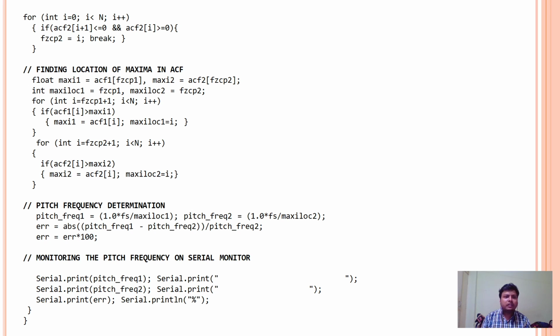So, if we consider the distance between the first zero crossing point and that first maxima, it would give the time or the distance after which the signal repeats its pattern, that is basically the period. Since we are doing everything in terms of samples, firstly we need to convert it into actual time. Since the signal was recorded at a sampling rate of 8,000, we need to divide by the sampling rate, that is fs, which is 8,000 hertz in this case.